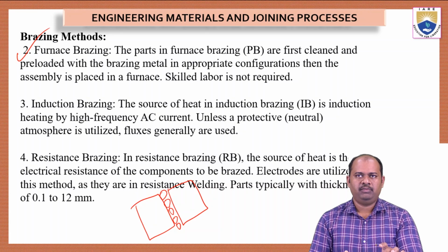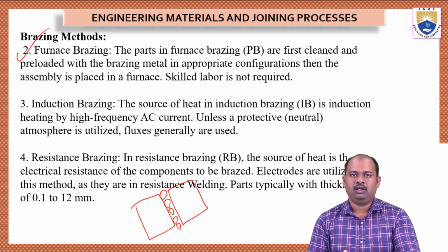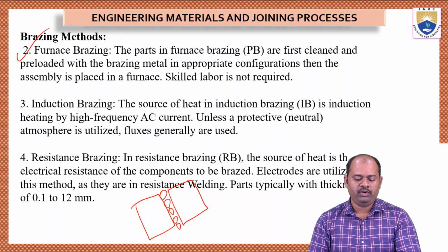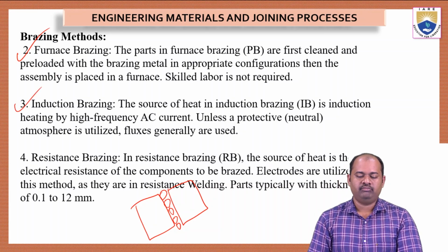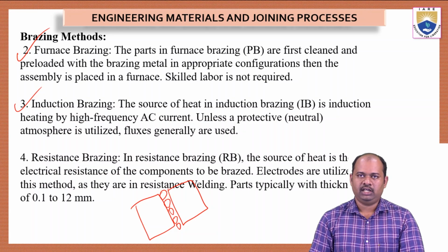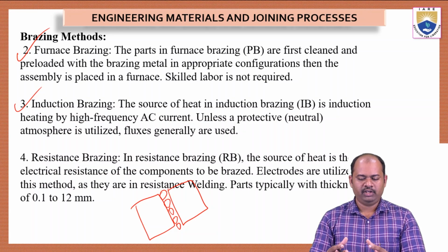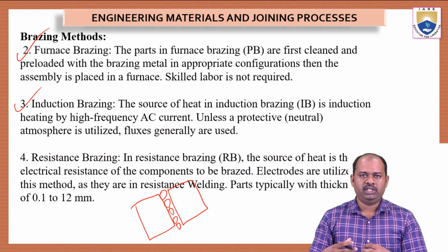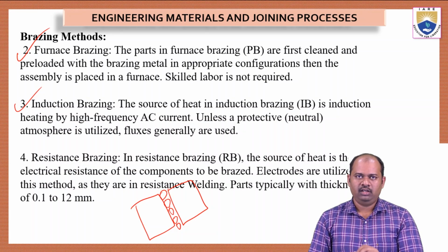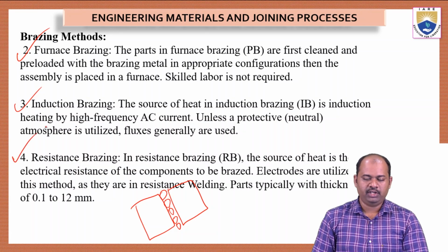So this is very similar to how furnace brazing is done. And then we have induction brazing. In induction brazing, the source of heating is induction by high frequency AC current. We will use this high frequency AC current for producing heat, which will melt the filler rod and it will form a layer.